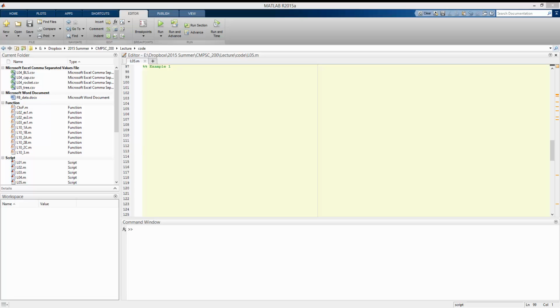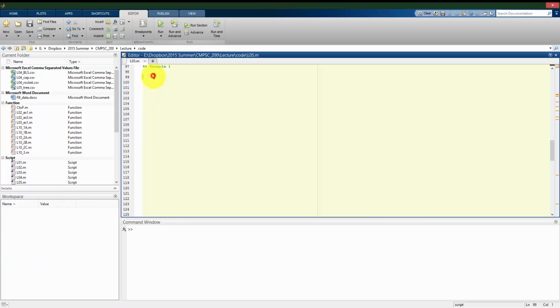So we have 1,000 data points that we collected from the tile manufacturer, and we can take the mean of that data, and it turns out to be 12 inches. For the horizontal cuts, we find that the standard deviation is 0.2 inches, and for the vertical cuts, we find the standard deviation of those 1,000 data points to be 0.15. Then we could put that data into some normality test like the Lilliefors test, and it would say yes, we can treat this as a normal distribution, and that's where we begin this problem. So we're working under the assumption that these lengths are normally distributed in order to do the rest of the problem.